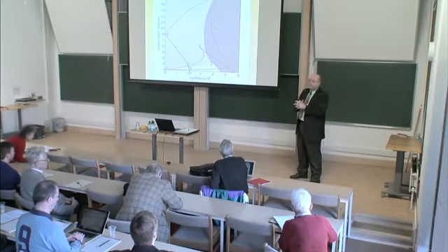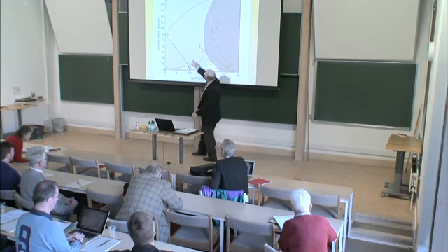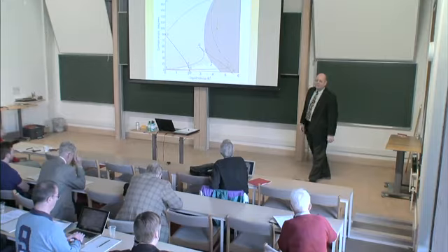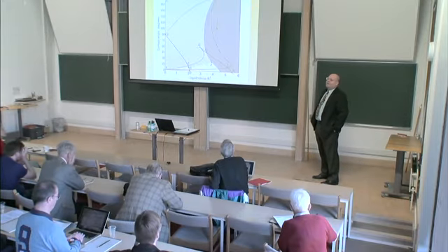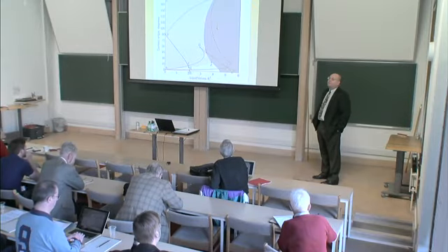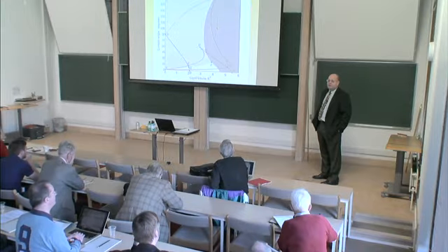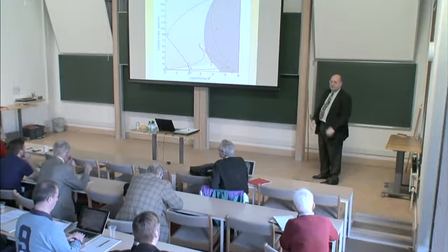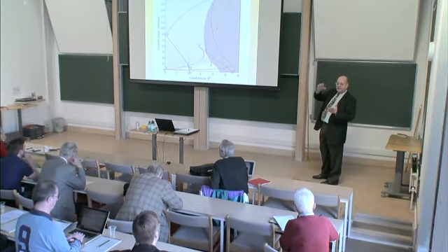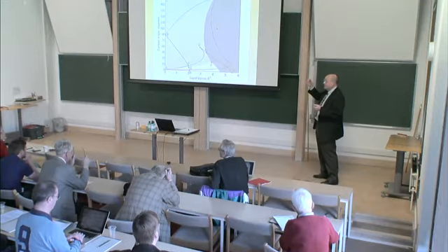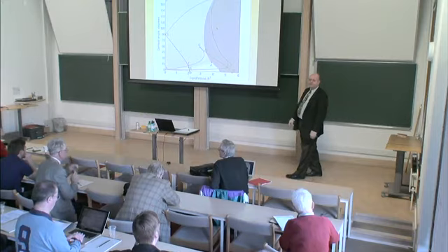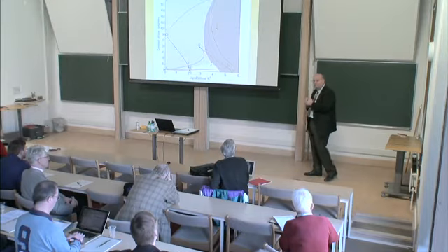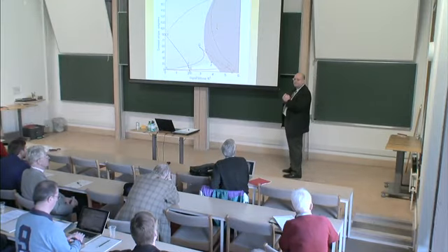But again, we could be missing a little region right here or something. Until you check every point, you don't know. But I haven't found any, nor do I see any reason to think that that would be the minimum energy solution compared to these that have a lot more of the volume in contact or closer to the wall, or wetting more of the wall. The bridge has very little wetted surface and a lot of free surface, and the wetted surface, at least for a wetting liquid, is what's reducing the energy. So it wants to wet more of the wall to reduce energy. Just intuitively, I don't see the bridge as an attractive option for the liquid.